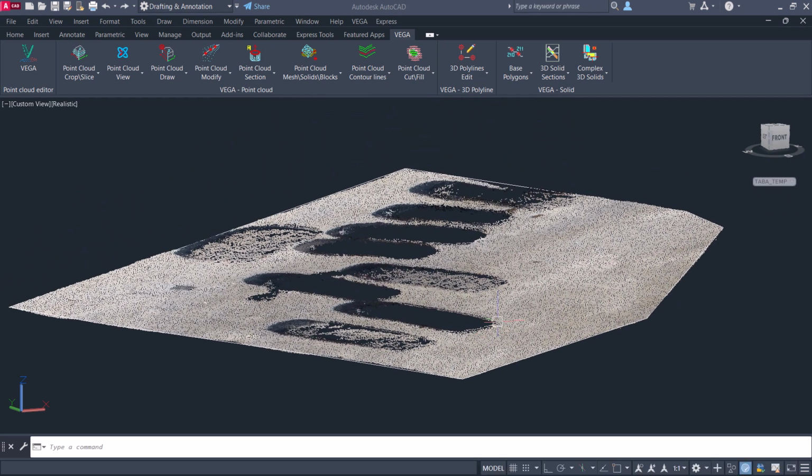As mentioned in the previous films, the VEGA program is not intended for editing point clouds. The VEGA program is intended for convenient and productive drawing on the point cloud within the AutoCAD program. It is intended for creating topographic maps, modeling buildings, calculating volumes, etc. The command described above does not need to be used often, because the VEGA program has the ability to ignore such objects during command execution. This means that there is no need to clean up point clouds and classify objects in advance.